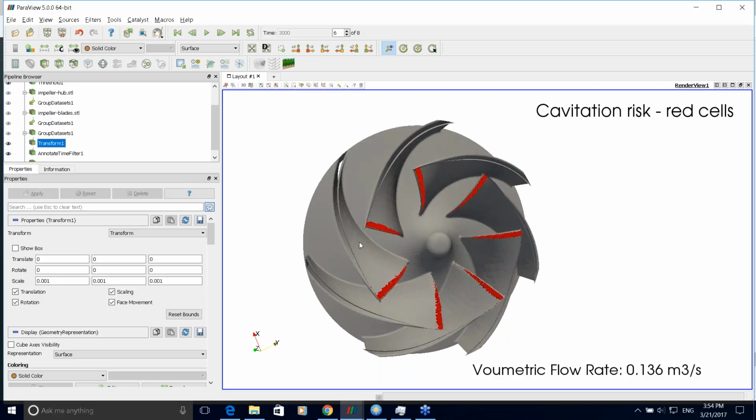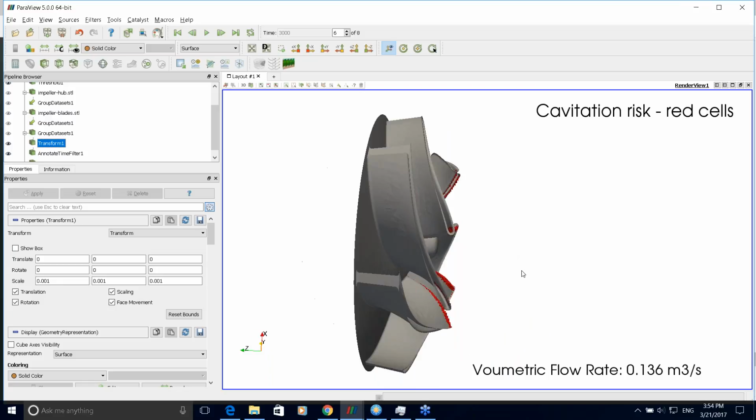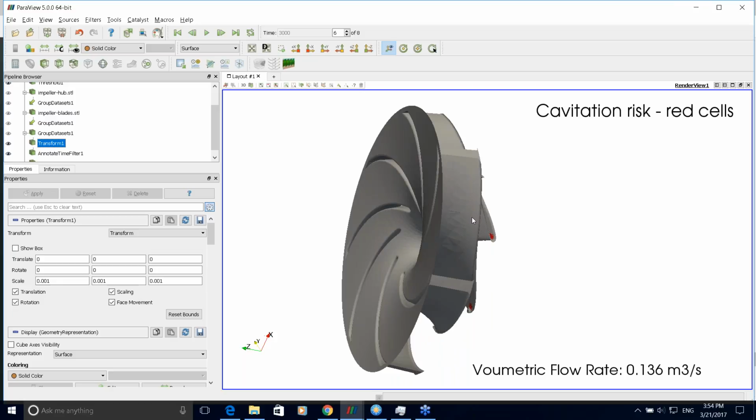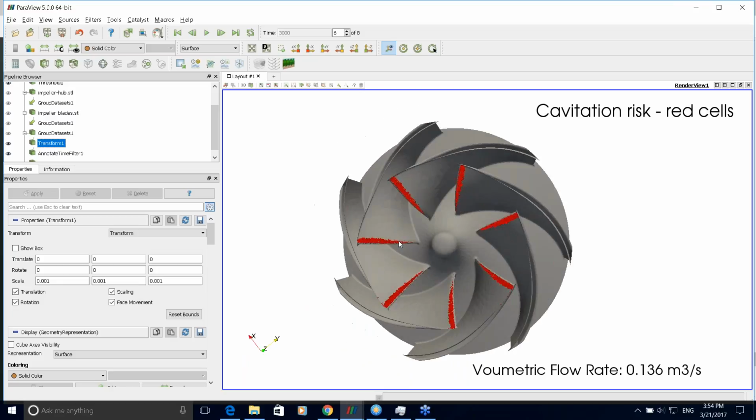You just quickly generate the STLs and the configuration file in CFturbo, and by a few clicks you are able to run the simulation and see the first results without any need of modification. I believe that using CFD for turbomachinery evaluation has never been easier in this way.